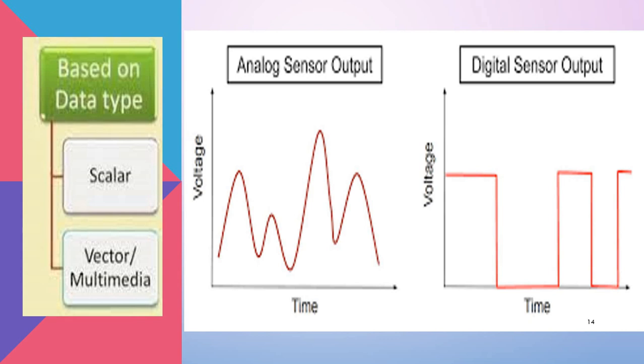And the next comes vector or scalar sensors. In this, the vector sensor measures and provides information about multiple physical quantities. Here the vector sensors utilize multiple sensing elements, to capture the different aspects of a physical quantity being measured. And the vector sensors output data in vector form, which includes both magnitude and direction information. The magnitude is represented numerically, and the direction may be represented in angles.